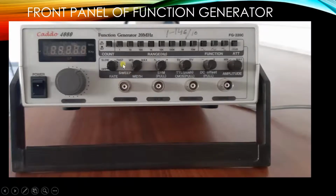This is the front panel of the function generator. Function generator is basically an input device for the CRO. The different frequency ranges are set from this function generator. Here these buttons show the different frequency ranges. It is 1 Hertz, 10 Hertz, 100 Hertz, 1 kilohertz, 10 kilohertz, 100 kilohertz, then 1 megahertz, then 10 megahertz, and this function generator goes up to 20 megahertz.